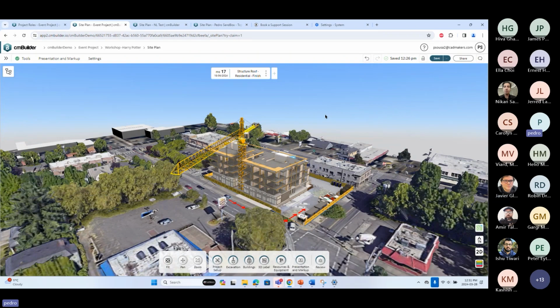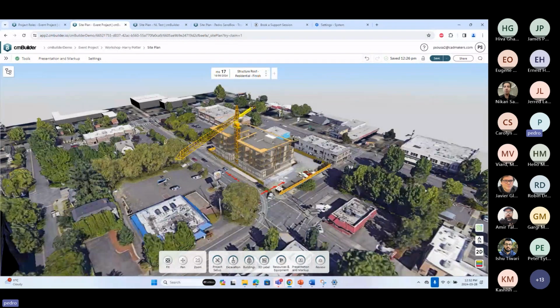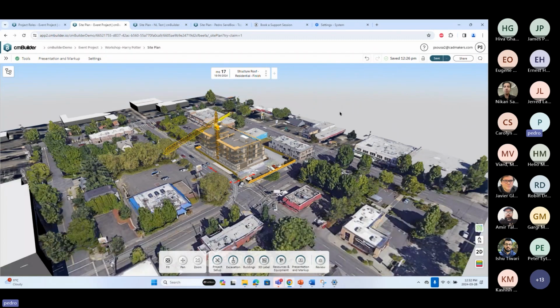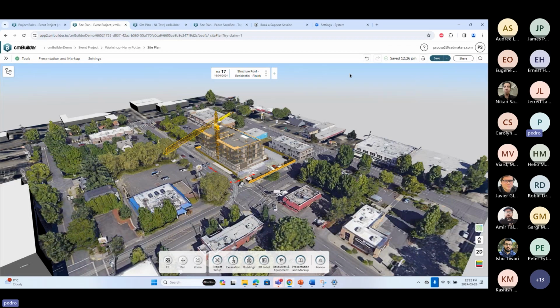And it's a good thing that CM Builder is running on the browser, because it keeps everything auto saved. Even if I had that problem that Javi just described, which is mainly caused when you have a scenario with a lot of different, heavily textured models like these trees over here, and you keep moving the browser window to another screen and going back and forth, you might get an issue that shows up over here at the bottom called WebGL context lost.